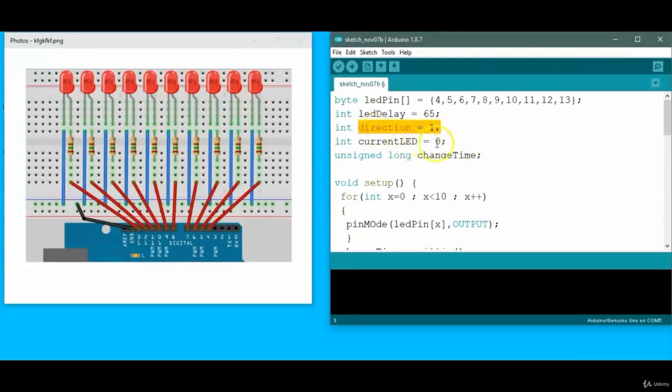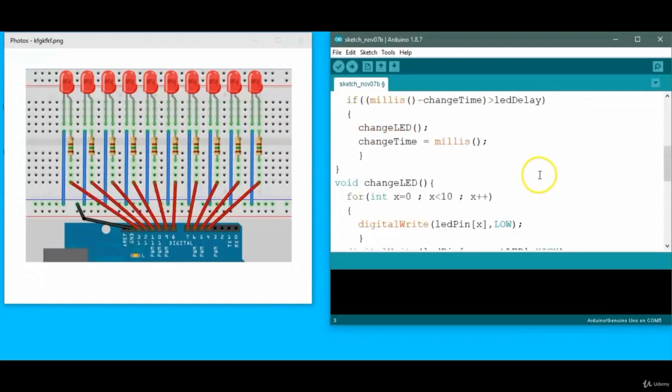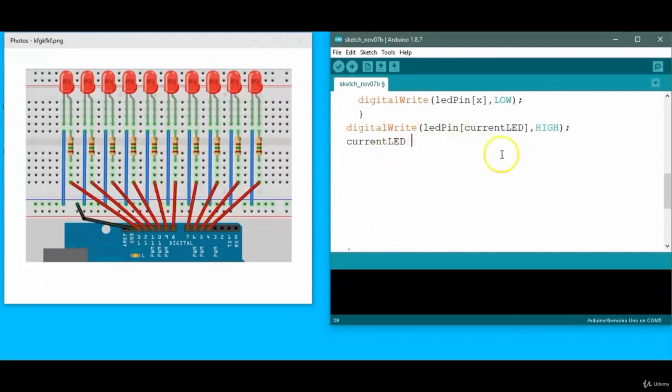It's actually a direction concept, that we go from 0 to 1 and then from 1 to 0, in forward and backward directions. I also forgot to mention the usage of analog values after writing currentLED: you can use different values from 0 to 255, that is the brightness value, so that the chase effect will be a little more beautiful.